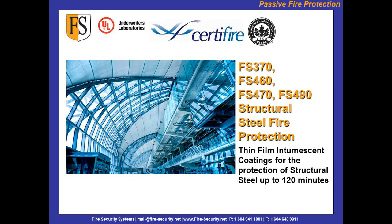What thin really means, well, an intumescent grows by expansion and insulates a structural member. The good thing about intumescence, not unlike our FS15 11 cable coating, which is an intumescent, is that they're all thin film and low build coatings. So they only require 1 to 2 coats, maybe 3 coats, and usually all are under 5 millimeters dry film thickness.